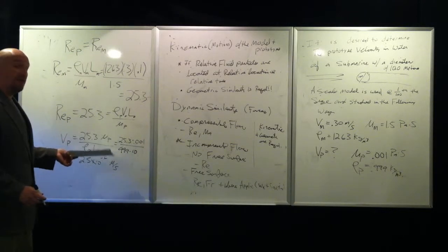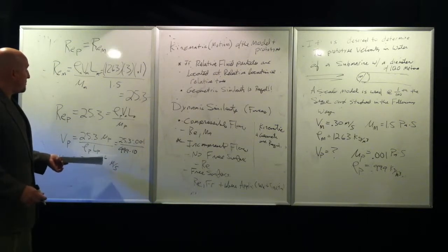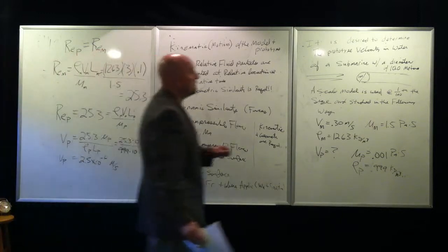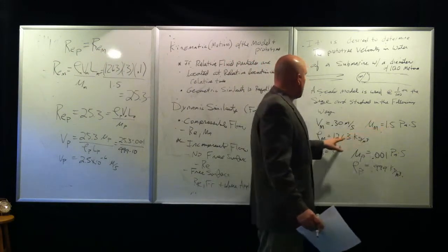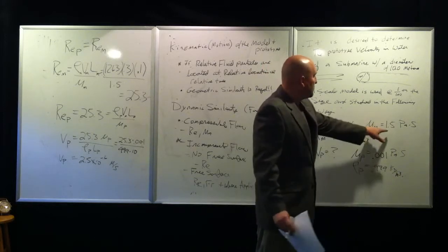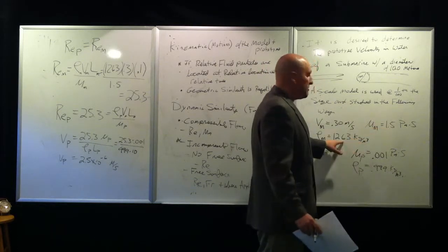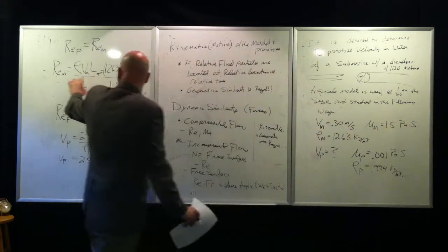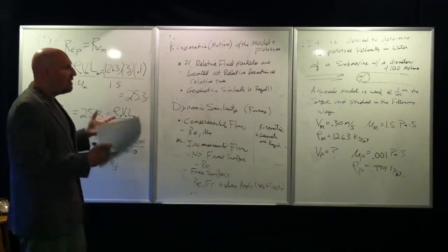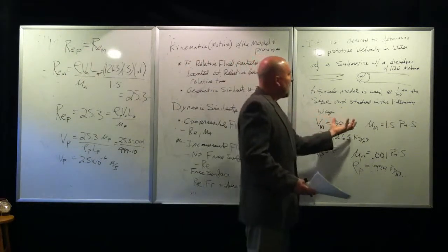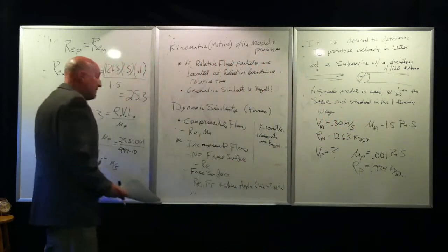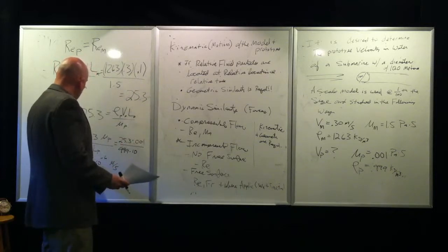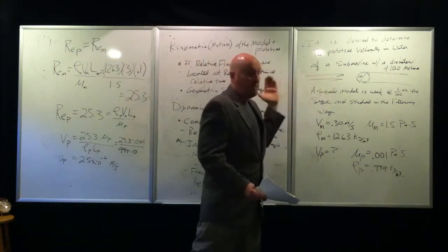So to go back and to explore where the parameters are going to be useful to what's going to be in the prototype, you can go back and choose a different material to perform your experiments on. You can change your viscosity, you can change the value of the density, and you can change the velocity. So therefore you can change the Reynolds number of the model. So this is the useful way to go through and perform the experiments to have a valid situation for your prototype.